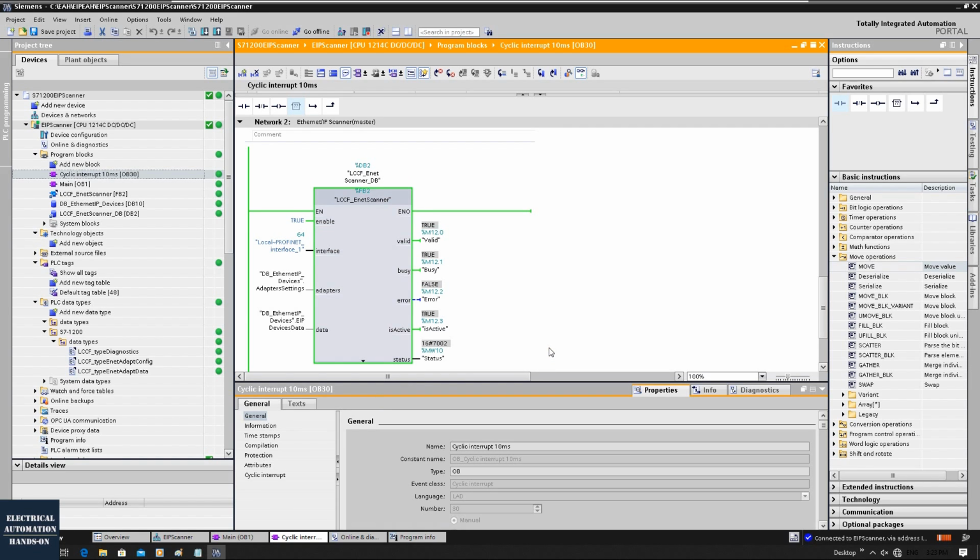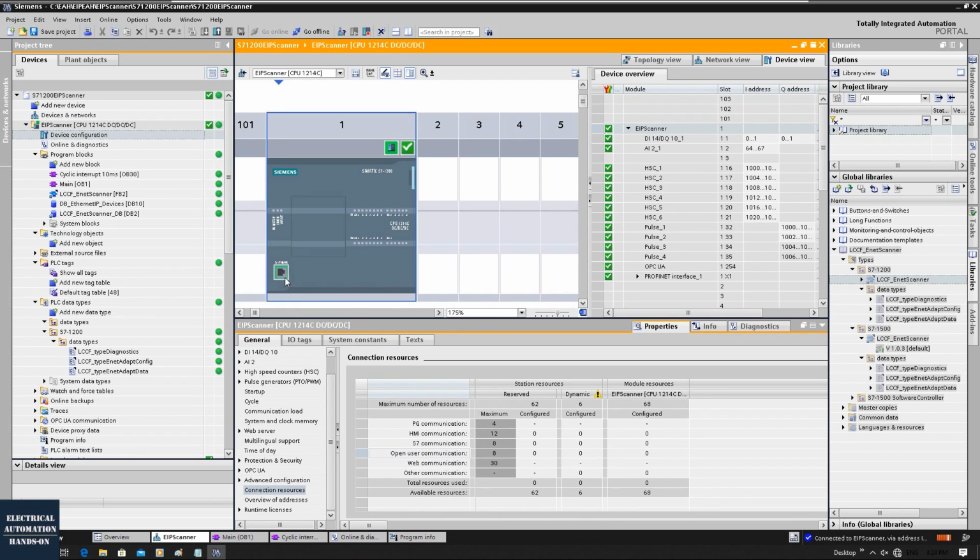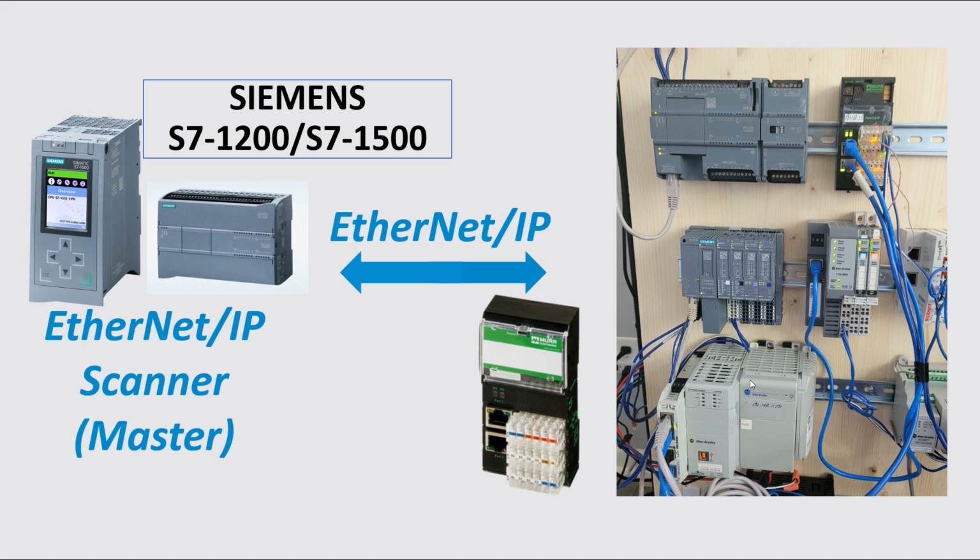But you need to be very careful. The maximum resources from this port is 8. And the PROFINET I/O is not included in these resources. That is the hardware portion too, so you do not need to worry about these numbers interfering or conflicting with the PROFINET communication. The PROFINET communication resources belong right here. PROFINET uses a dedicated microchip to do the job, so the resources here won't cause trouble for PROFINET.